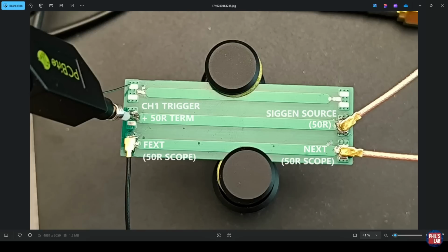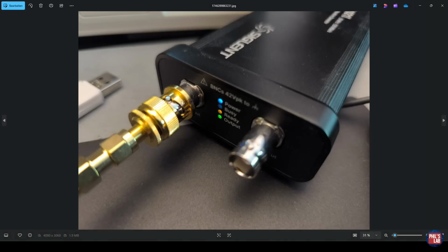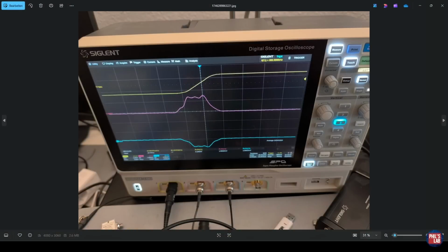So a very, very simple setup. The traces are quite far apart and therefore we won't see terribly much crosstalk, but we'll be able to examine the effects of frequency, rise time, and look at near-end and far-end crosstalk and their differences and similarities. For the signal generator, I'm just using a Siglent standard wave generator which can be controlled by my oscilloscope, which is this Siglent SDS6204A, where I have 3 channels set up as we just previously talked about.